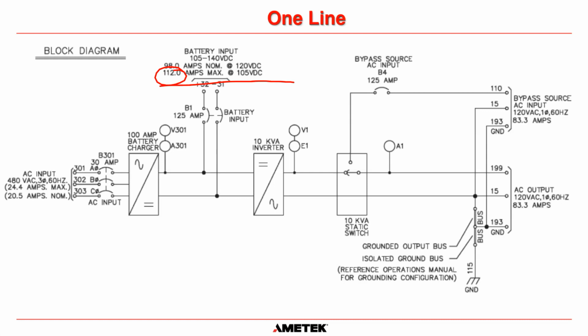And obviously, if you're running it in cable tray or conduit, you've got to do all the calculations to work out what the best size of cable is for that particular current. But that is the maximum that the system will see, and basically, that's at the lowest voltage, the low battery disconnect voltage. So 112 amps is the max current the battery should see.